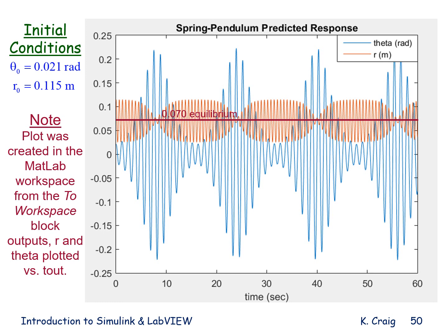However, in simulation, everything is perfect. So if you pull it straight down with theta being 0, you will get pure spring mass vibration, motion up and down, and there will be no theta motion. So I give it a little displacement in the theta direction, so I will get, again, transference of energy from one mode to another mode.